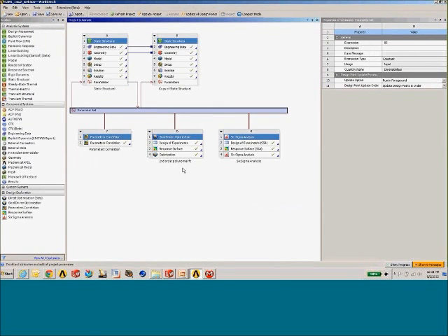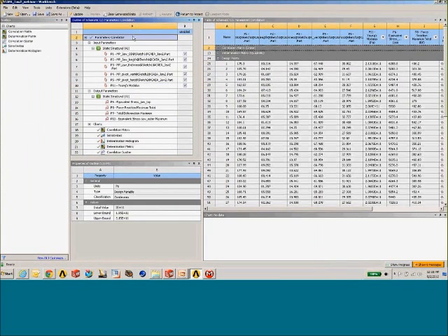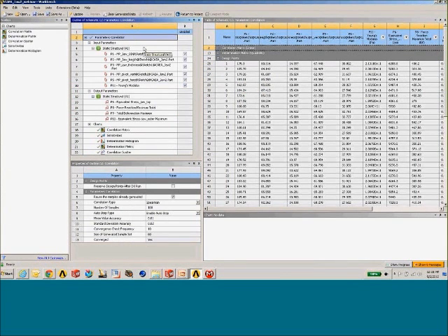And what we'd like to do is begin by identifying which parameters we think are critical to the design. Now we can use the Parameter Correlations tool down here under the Design Explorer menu in the lower right-hand corner of the screen. We drag and we drop that onto the page, and then we double-click on it to open it up. Now the Parameter Correlation tool will basically generate for us a set of design points, generate the solution, and then supply back to us a measure of the degree of strength of the change in the input versus the response of our system.